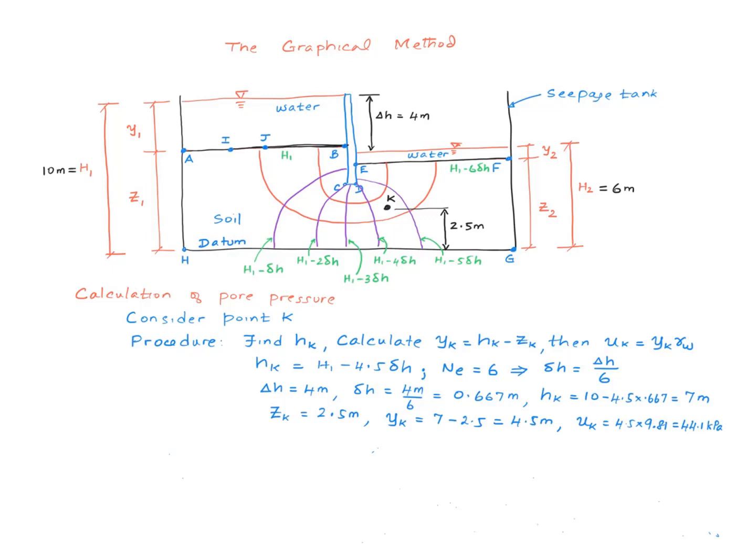And then if I were to calculate the pore pressure at this point, I need to follow this procedure for calculating the pore pressure at that point because there is water flow taking place now. And similarly, I calculate the pore pressure at point C by following this procedure. So now I have the pore water pressure at discrete points inside the soil with water flow.